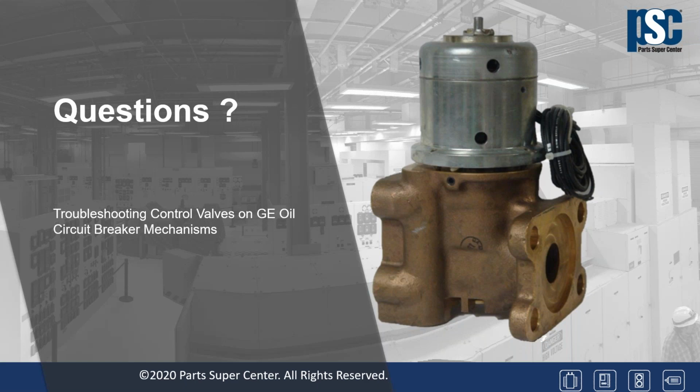If you want to give us the serial number of the breaker, we'll make sure we get you the correct instruction book. The other thing that will adversely affect the opening or trip time, more frequently, is the lubrication in the mechanism. Quite often, the original organic-based greases that were used tend to get hard and oxidize over time.